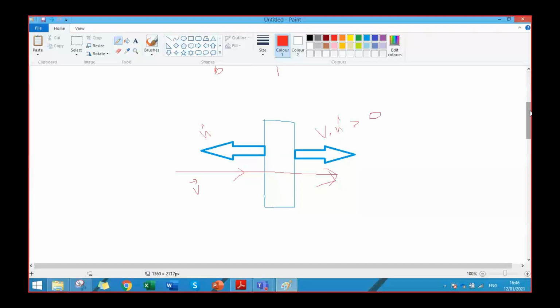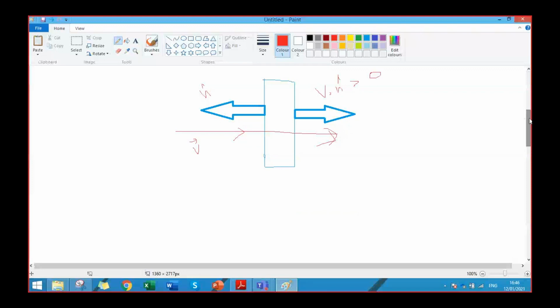Yes sir, clear. Moreover, this v dot n will solve many other problems. Let's say the control surface is inclined like this. The area normal would be like this, right? And if the flow is horizontal, it means that the whole surface is not participating in flow. So v dot n would be equal to v cos theta. It will automatically account for the amount of flow, because the flow beyond this area would pass above, and that will not contribute to the control volume.